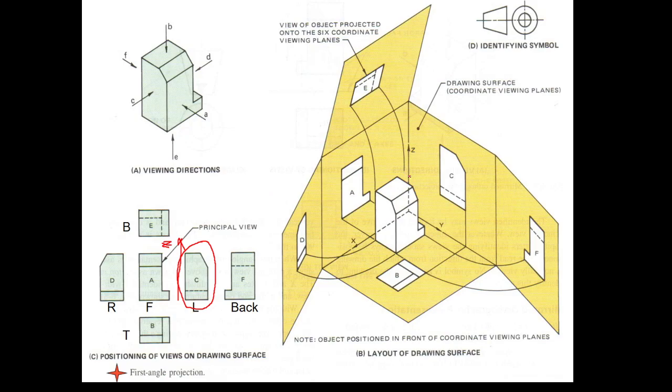Yes, as can be seen here, the folding line coincides with the Z-axis of the coordinate system. It is between the frontal picture plane and the primary profile picture plane, on which, in the first quadrant projections, we obtain the left side views.